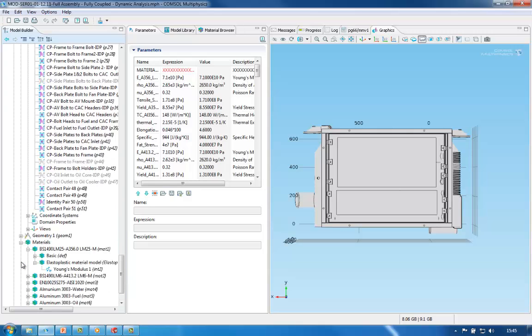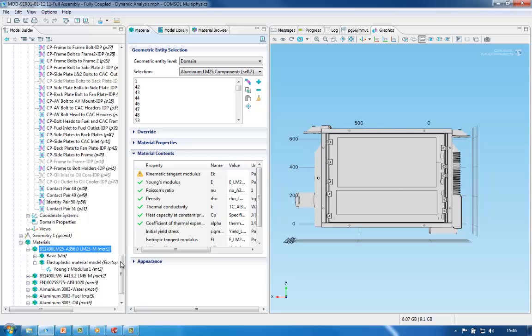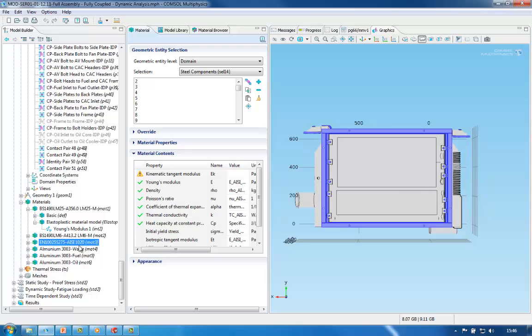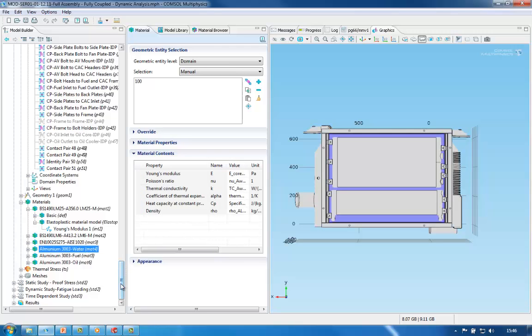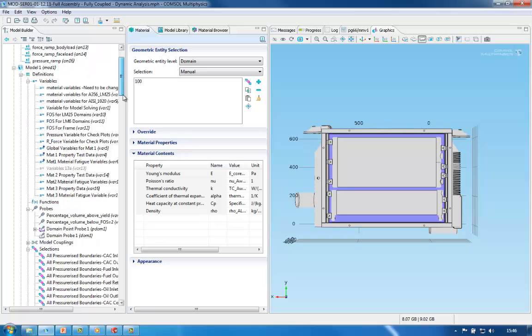Having so many components and each operating at different temperatures, the material characteristics are not easy to set up for thermal fatigue. Thanks to COMSOL, using the function feature inside the material section, we can make material characteristics temperature dependent. Having made the selections before and with the material parameter set, implementing the material properties for different components is made even simpler. Since we performed fatigue analysis of the system, we also have SN curves set up to help us analyze the fatigue life under various loads.